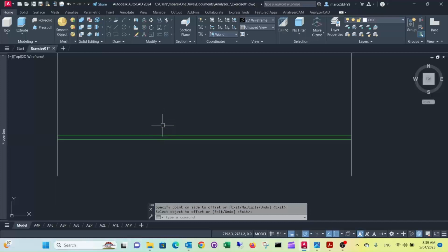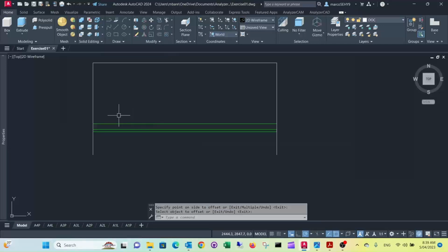And it's probably a good idea to put the line for the plinth as well. That one is 50 mm further back. Another good thing is putting in the side scribes. In our instance, we want to do them 20 mm as well.